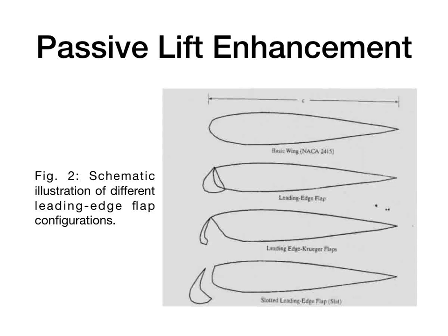They are also usually located over the outboard half span of the wing in order to reduce the potential for wing tip stall. The optimum leading edge flap deflection is up approximately 30 to 40 degrees.